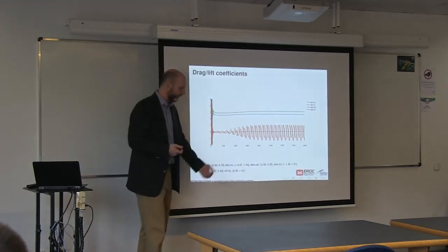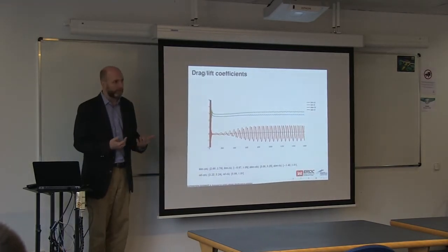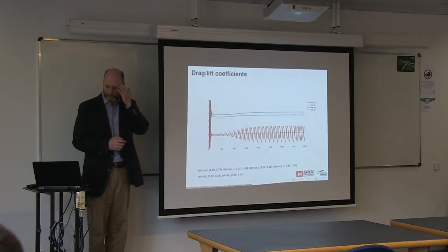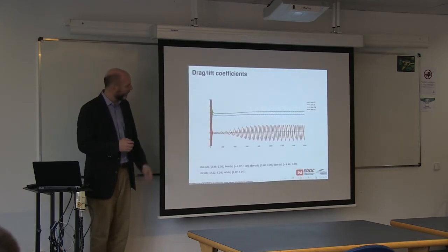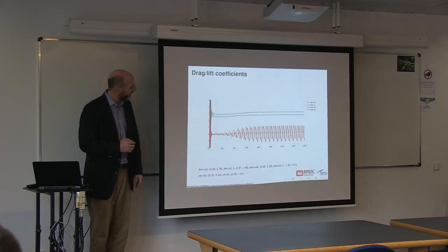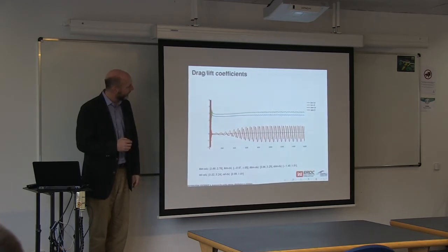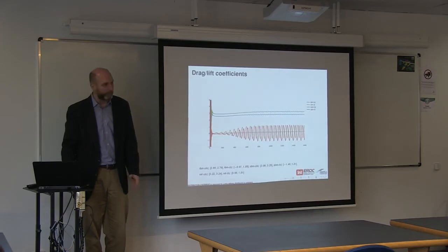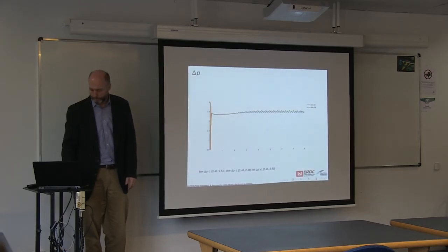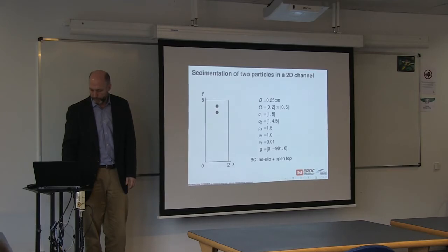But the phases of the vortex shedding are, of course, very sensitive to the mesh, and so that's a little bit to be expected. But clearly we have some work to do. We may have a bug in our SBM method, but there's still some sensitivity to these different approaches that we don't quite understand. Also, pressure drops are relatively accurate, but with some small differences.